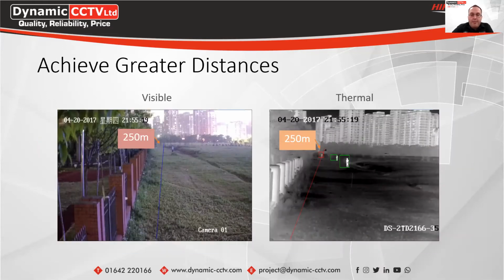With the thermal cameras, we generally recommend them especially for perimeter guarding. So if you've got a long perimeter fence line and you need to see anyone that crosses the line, using line crossing VCA, for example if they jump over the fence or breach the perimeter. With standard optical images, it's very difficult to get longer range detections. You can see there at 250 meters, you can't really see the person, so you wouldn't be able to get an accurate reading with standard VCA rules on optical cameras.